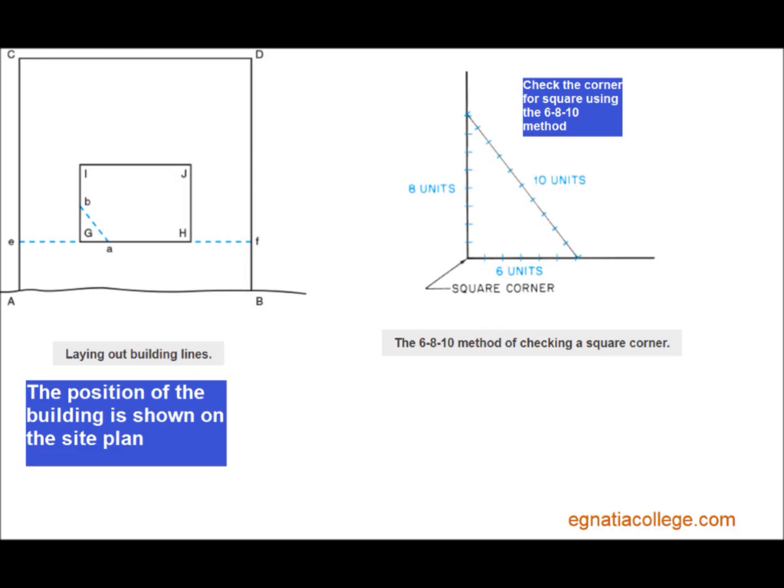Next, measure the side setback, which is the distance from the side of the property to the side of the building at stake E to side of the building, line EG. Drive a stake where the side setback and front setback meet. This stake represents one front corner of the building, corner G.